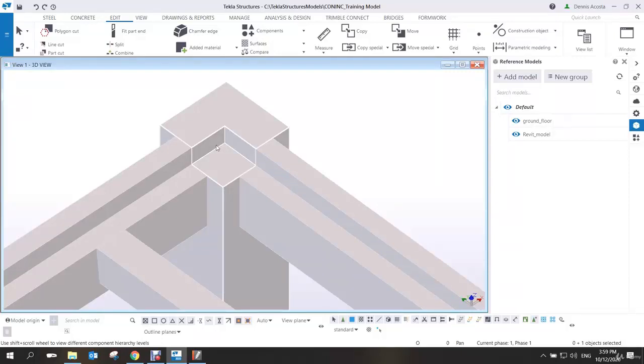as a parametric cross section. But if not, we can still convert this, but as an item, because there are two different ways of conversion in Tekla. One is the extrusion, which is a good conversion. If it is converted as extrusion, it means you can change the size later on in Tekla. But if you convert this as an item, then it will be a fixed profile, meaning you cannot change the profile size.